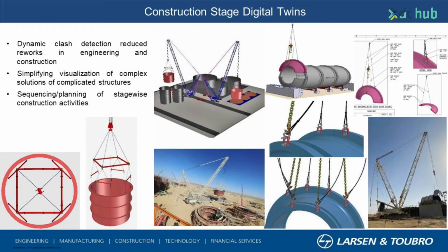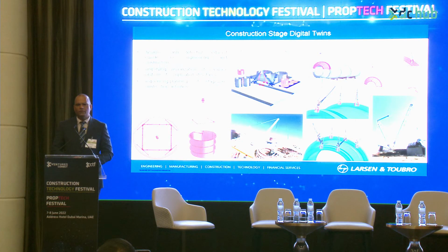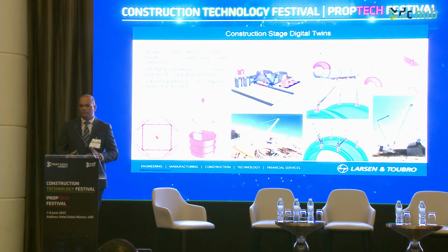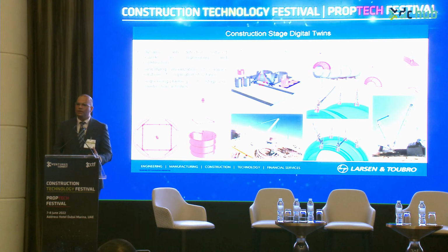We've used digital twin extensively for doing erection rehearsals. You know, it's always very complicated when you do heavy lifts in excess of 200, 300 tons and by using mega cranes. We've always seen challenges, we've always seen issues coming up during the final assembly. And so what we did here is we built the whole model on a digital platform with the digital rehearsal, making sure that the clashes are checked, making sure the crane movement is properly analyzed, the placement of the crane. So what was earlier done on 2D drawings is now done on 3D platforms.